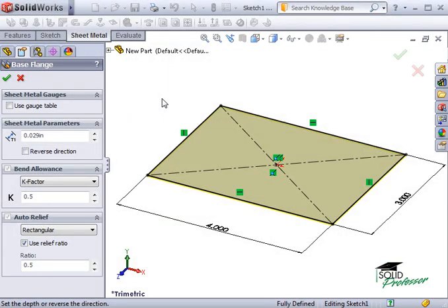If you work with sheet metal, I'm sure you're familiar with bend allowance and the many different ways of calculating or estimating the developed length. SOLIDWORKS now allows you to define equations for calculating the developed length through a bend calculation table. Some designers prefer using this method because it takes more parameters into consideration.